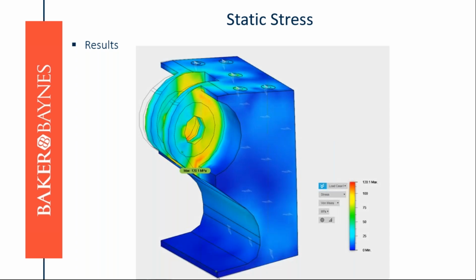If you look at the stress side of it, the von Mises stress, we can see here it's 120.1 megapascals at the maximum point. Von Mises is a stress value used to determine if a given material will yield or fracture, right? It's mostly used for ductile materials, and there's a yield that we have to look at and pay attention to here. And there's specific limits that we can work off. Sometimes it's elastic, upper limit, lower limit, and so forth, right?